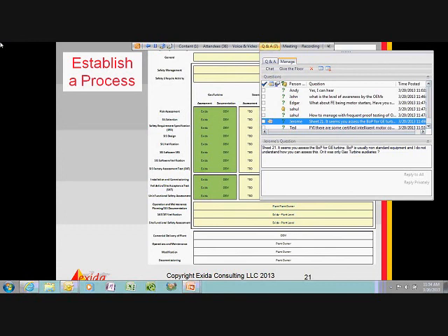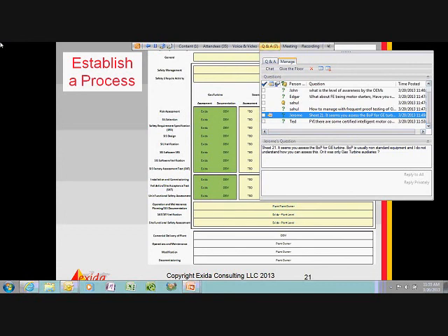So ensuring that 61511 was applied, that a HAZOP was done, and that hazards were identified and mitigated as necessary, would be part of looking at the balance of plant. Or if there were auxiliary boilers in the balance of plant scope, then you would look at those. So it's not that there would be a 61508 certificate or a standard certificate for balance of plant, as there would be for a gas or steam turbine, but in a plant review you would look at those and make sure that was done.